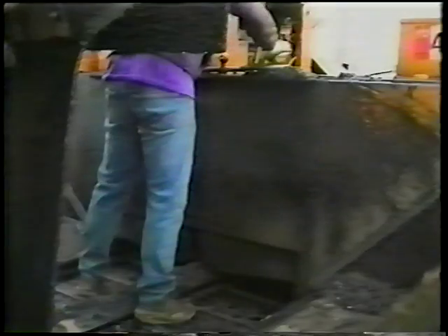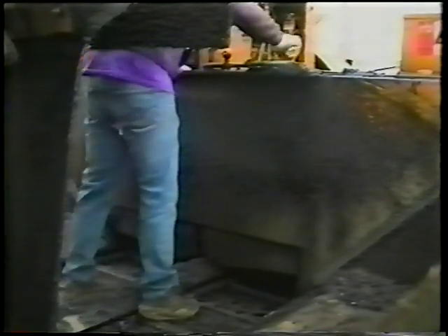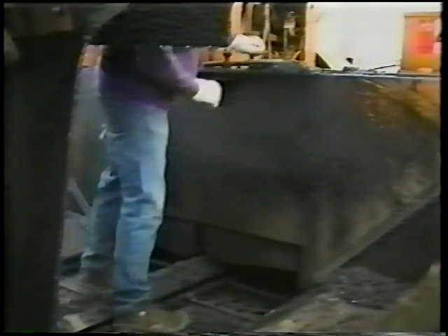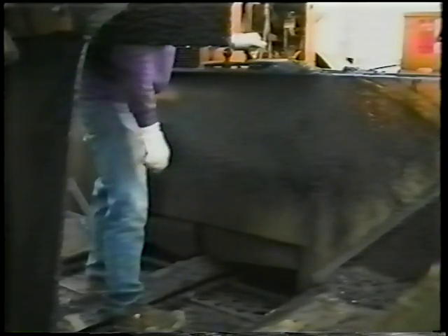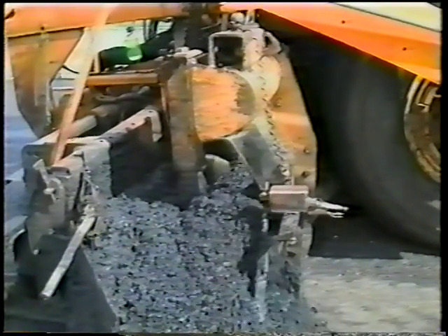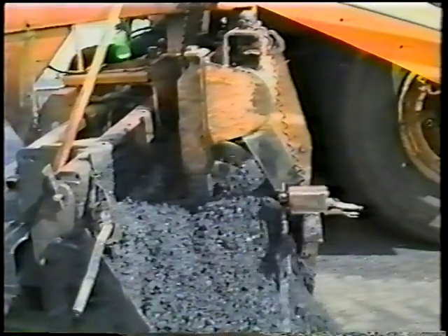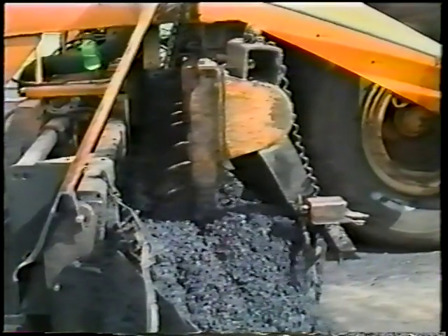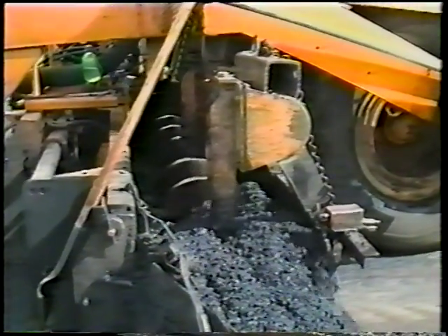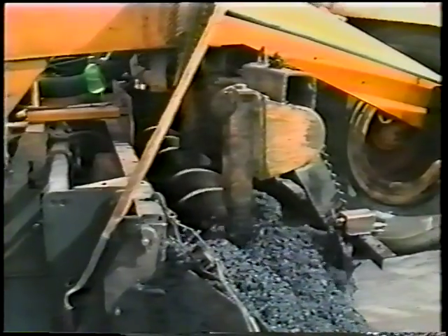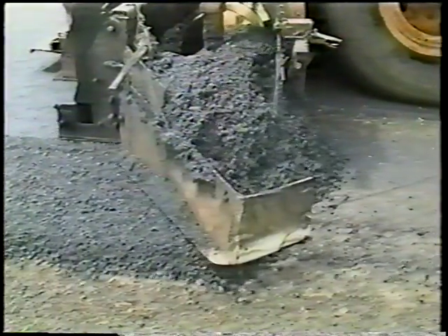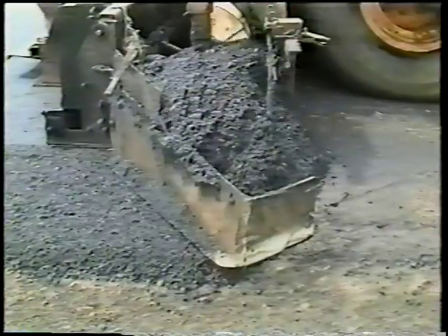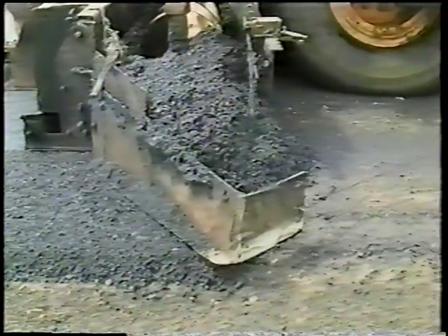Inside the hopper, two flight chains carry the mix through the tractor. The flow control gates over each chain are adjusted to allow the right amount of mix to pass through. As the mix comes out of the back of the tractor, the auger distributes it evenly in front of the screed. On many pavers, paddles are mounted at the center of the auger to keep material flowing toward the edges. A slope shoe, like you see here, may be attached to the screed to bevel the outside edge of surface courses.